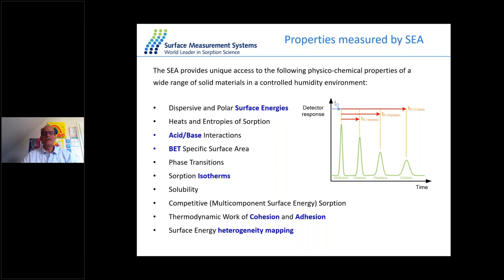How long does it take for the different organic molecules to reach a flame ionization detector, the FID? That retention time is proportional to the surface energy, to the interaction of your material with the different organic, vapor molecules.